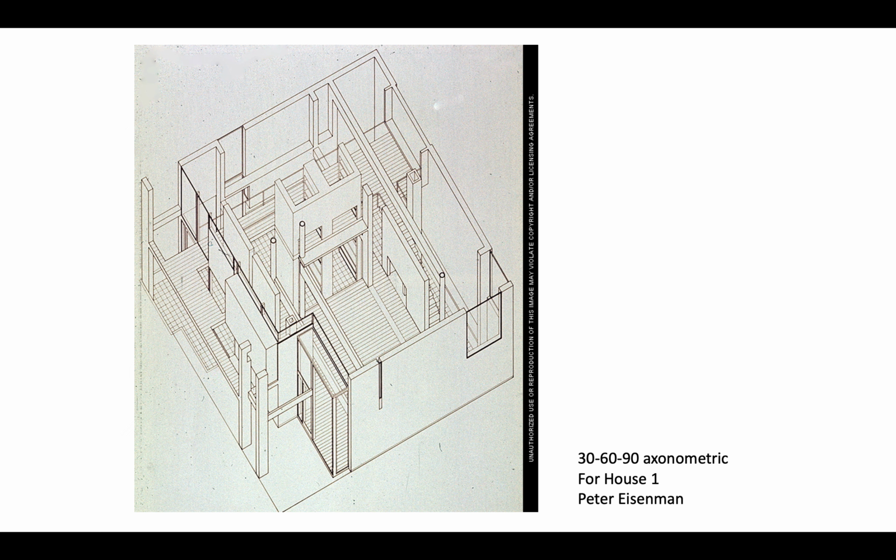We can also start to see different materials and line weights that he's using here, different line weights to create emphasis for windows within window frames, different emphasis to emphasize column tops. Here the line weights are starting to communicate those differences, and then thinner line weights to represent flooring material or tile in the case here of floor coverings and the like.